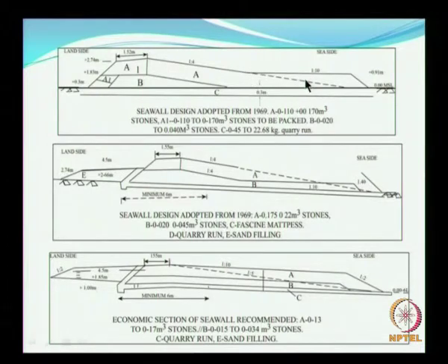So this is going to allow the phenomena of shoaling as well as the percolation of the waves. Because of the permeability of the armor layer, you expect a gradual decrease in the wave energy, and then what you have here is only a small amount of energy, just something like a run up over the structure.